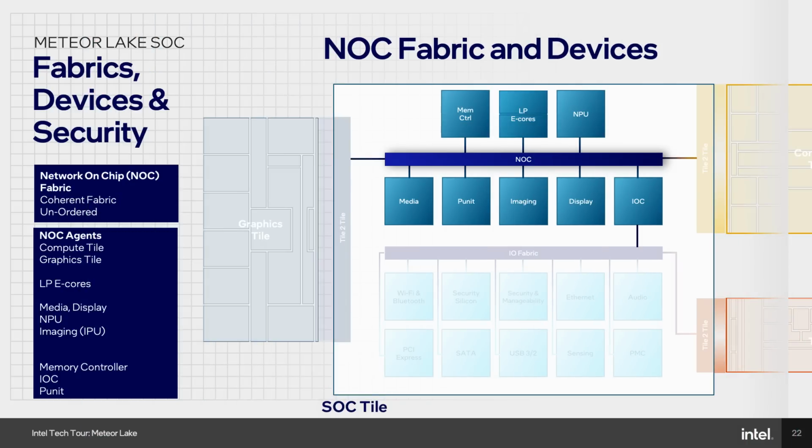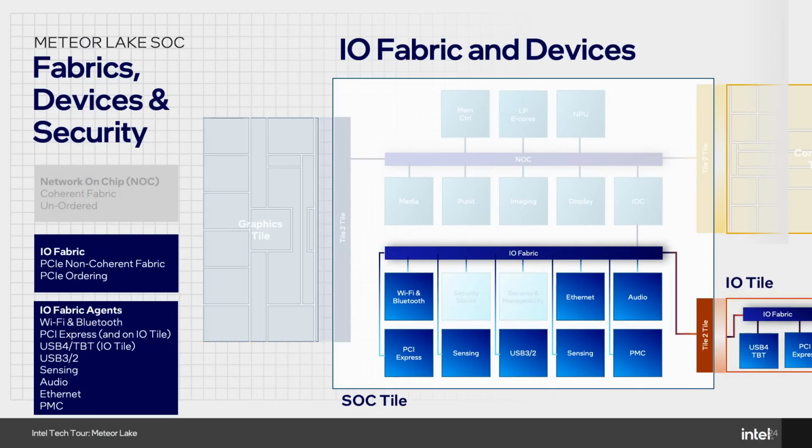The other thing we did for power management, we optimized on the fabrics themselves. We wanted the fabrics to be very dynamic based on the workload and the performance. With the disaggregation, we increased the size of our fabrics to have better performance. We have some additional traffic going between the tiles themselves, but we also focused on the power management to do this. The best way to think of this is if a workload demands lots of bandwidth between one or two tiles, we can optimize the fabrics between those tiles while the other tiles can be in lower power mode. And so this allows us to have the flexibility to adjust our fabrics to address the bandwidth, the speeds, and the performance we need based on the workloads that are there.